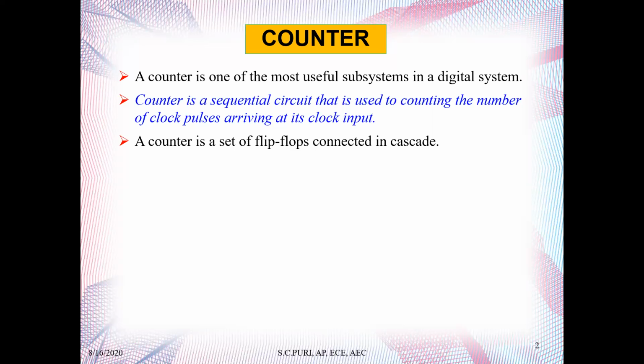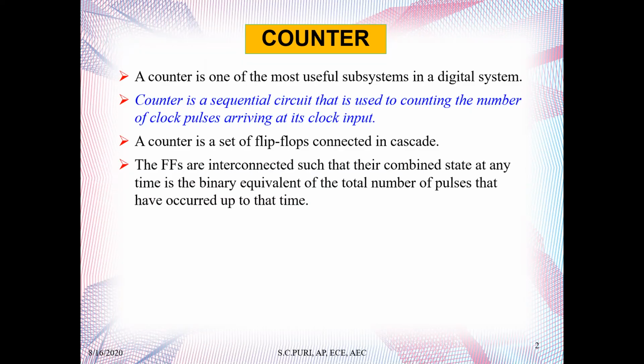A counter is a set of flip-flops connected in cascade. The flip-flops are interconnected such that their combined state at any time is the binary equivalent of the total number of pulses that have occurred up to that time. Thus, as its name implies, a counter is used to count pulses.